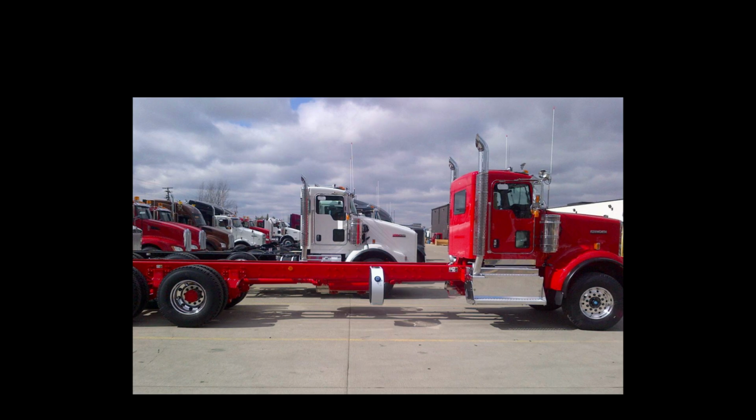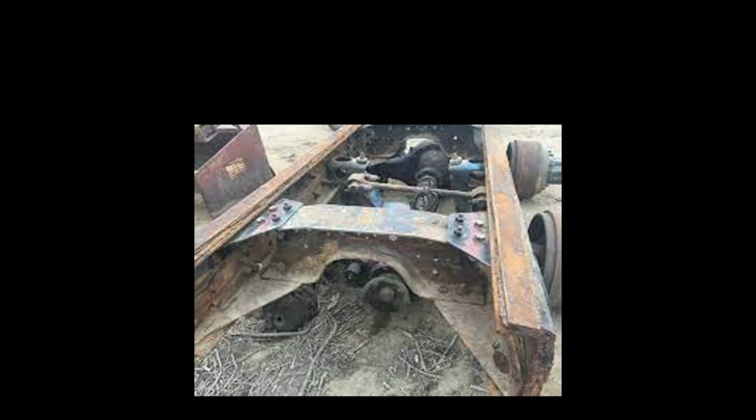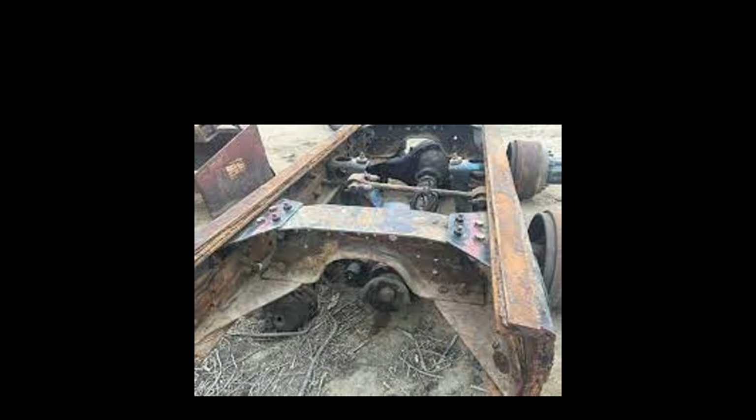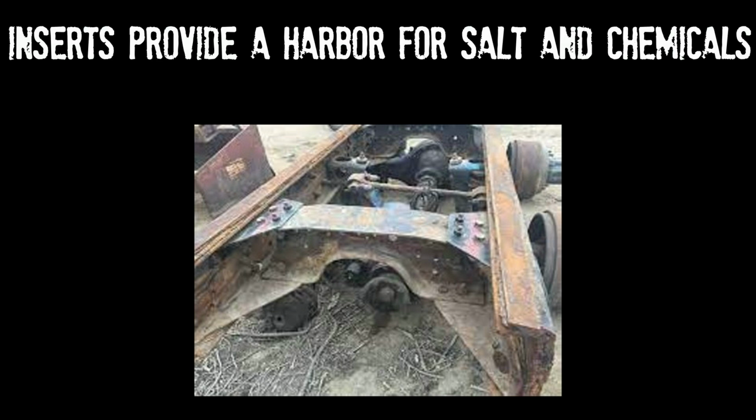Timing is crucial, as cabs and sleepers are built and painted days before frame rails are assembled for the same chassis. Rails arrive at the factory pre-treated, usually with prime paint. Some manufacturers offer additional treatments, such as zinc phosphate, e-coat, or powder coating. These treatments protect against road salt, chemicals, and rust, adding longevity to the rails.